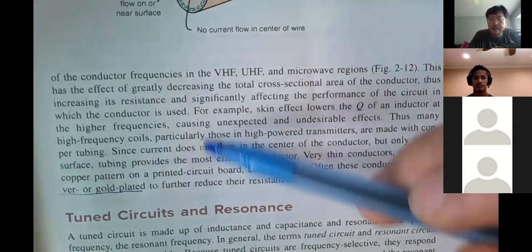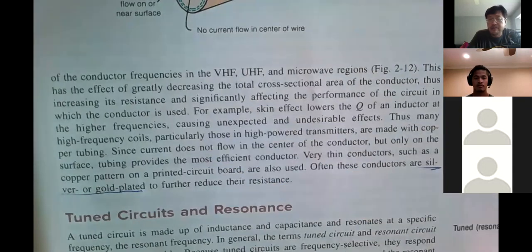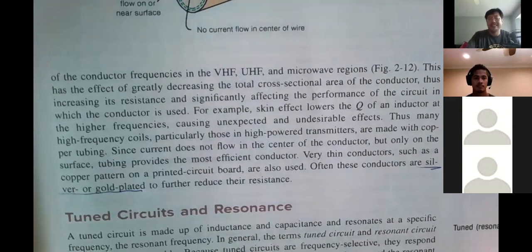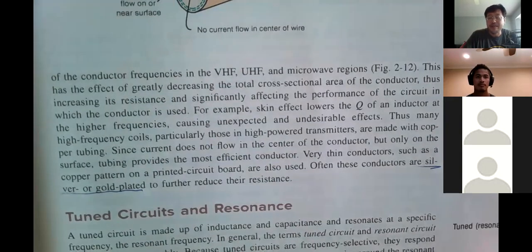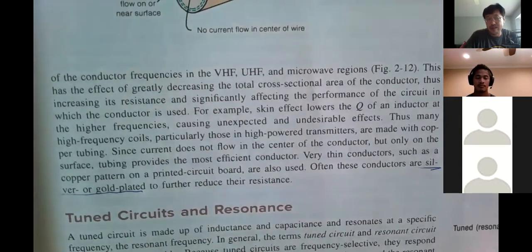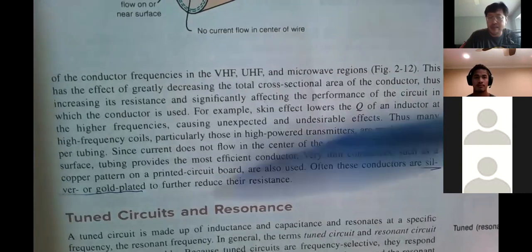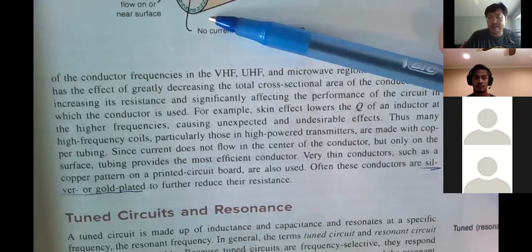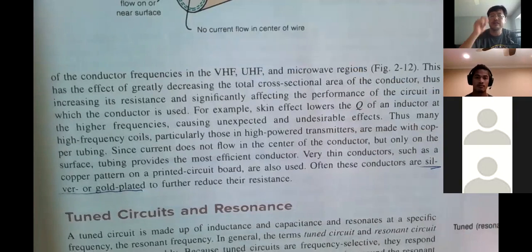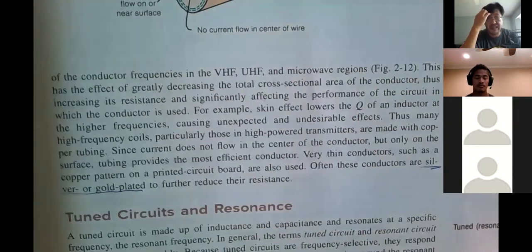Why do we coat it with gold? Because you're rich, right? Cover with gold. Actually, gold stabilizes your conductor because gold is extremely stable. So in some tough environments, when you coat your conductor, it's not because it looks better, right? For engineers, we do things not because they look good, but because the performance is good.